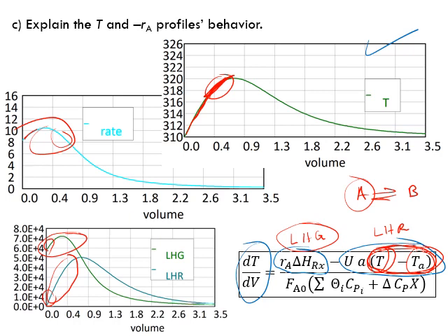Until we reach a point where the localized heat generated equals the localized heat removed. See, we are at this point. Okay? So we said the localized heat generated is decreasing because the rate of reaction is decreasing. Okay? Due to the decrease in concentration of A and increase in concentration of B. And we said the localized heat removed is increasing because of the increase in temperature inside the reactor, therefore the increase in the driving force for heat transfer. So we are here now, they are equal.